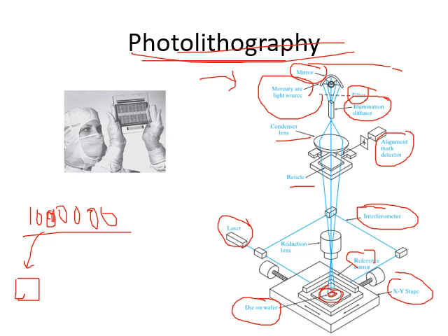For etching, actually we will cover the etching part, but for etching a few solutions are used. NaOH, which causes, depending on positive photoresist or negative photoresist, the etching process to happen. That means whichever part has to be removed or etched away, that part will be removed by this solution. In etching also we have different types, we'll come to that.